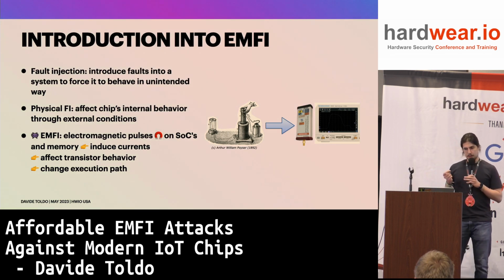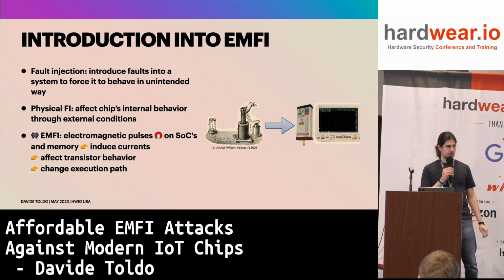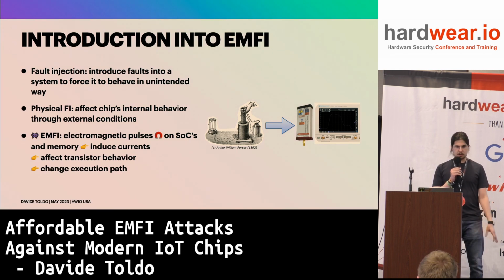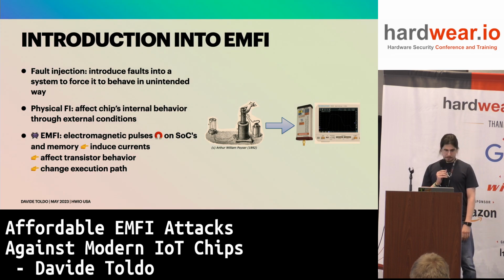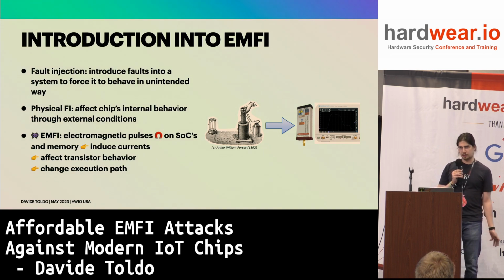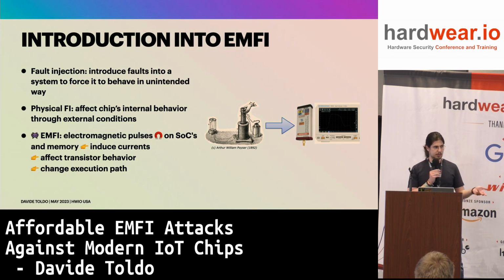And if we do this very localized, we can affect very specific areas of the chip and very specific instructions or memory regions or registers even. By affecting the transistor behavior, like flipping a bit or skipping an instruction, you modify the program flow, even though the code is actually secure.